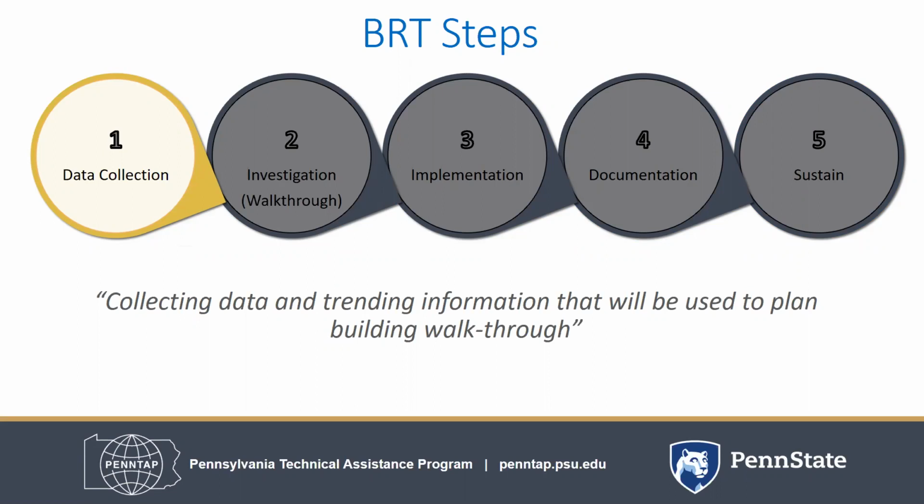For example, consider a utility bill analysis. Look at your facility's current energy assets and energy consumption. Before even considering changing out the filthy blocked air filter, you should look at your existing energy use of your system to understand, as much as possible, the existing profiles exhibited and any causal relationship you can identify. Benchmarking your energy consumption will give you a better understanding of where your energy is going, and it will help you identify where to focus your attention.